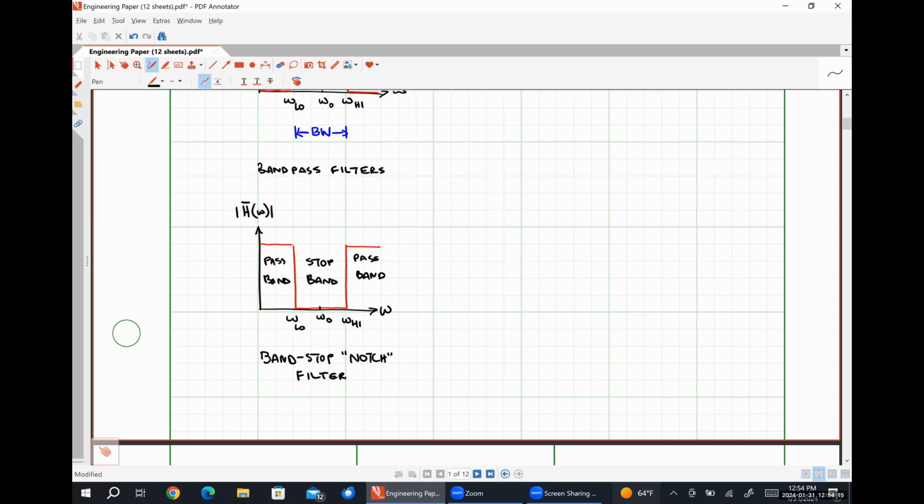Isaiah, how may I help you? For the band pass filter, omega naught, the frequency difference looks all the same thing for this. Absolutely. Yep. Still the resonant frequency, which by definition is the frequency at which the impedance looks real. So effectively, all of the reactance contributed by the inductance will be exactly canceled out by the negative reactance of the capacitor at this particular frequency.